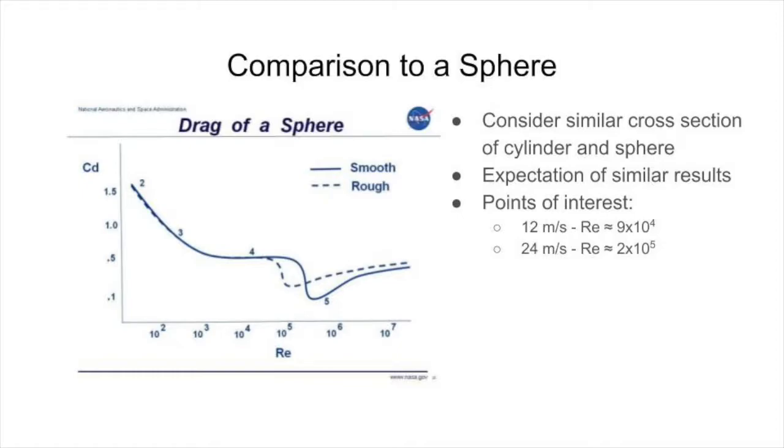Further, at a Reynolds number of approximately 180,000, both the smooth surface and rough surface have similar drag coefficients, with the rough surface being slightly higher. Again, a comparison to the chart adds validation to the experimental results, suggesting at this speed an intersection of the drag force of a smooth versus rough surface.